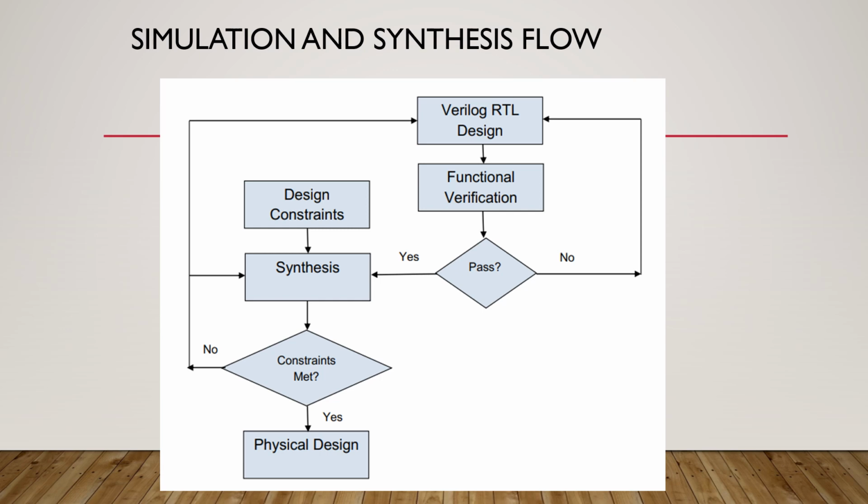What is meant by design constraints? The design constraints mean area, power as well as speed. So depending upon our application or requirement, here we have the area, speed as well as the delay, right? These three requirements we have to concentrate on at this stage. The synthesis tool will produce all these details at this stage.